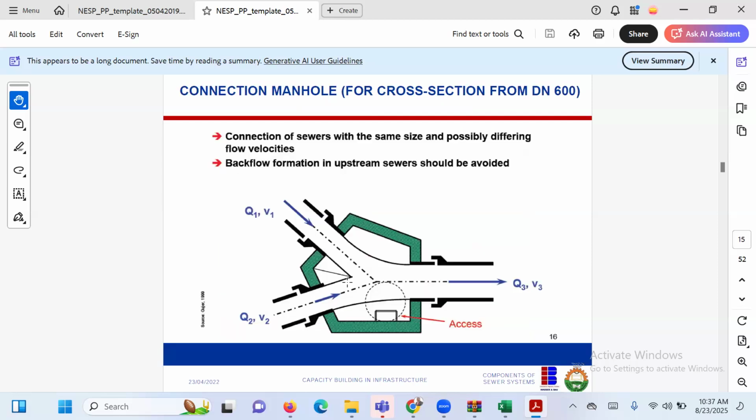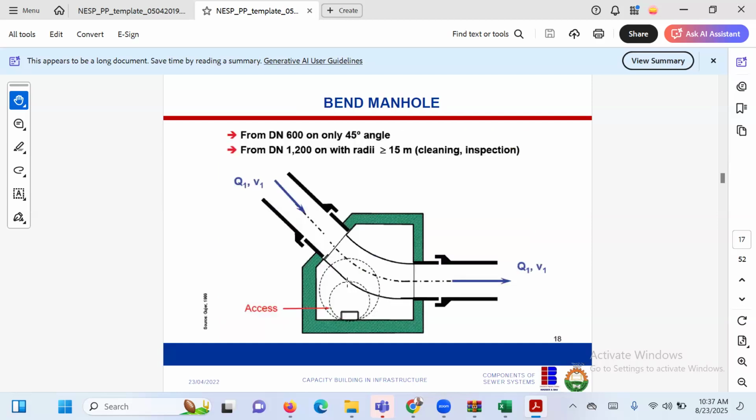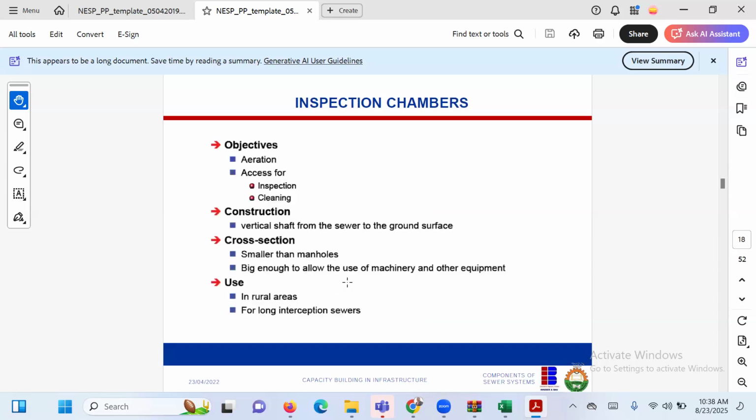So for this one, you can see that this is a typical stormwater drain, underground stormwater drainage. Some cities, when they don't have space on the surface, go subsurface for their stormwater, especially places like Paris, where the metro stations and many things are all underground. So the sewer also goes underground. It's advisable that your bend should be at an angle of 45. There's nothing like angle 90; you must not do angle 90 in pipe.